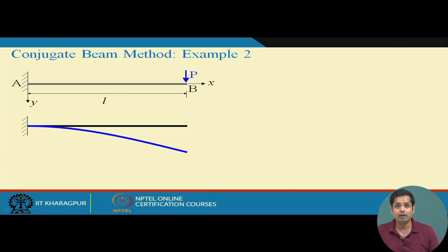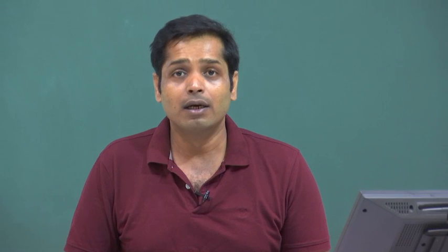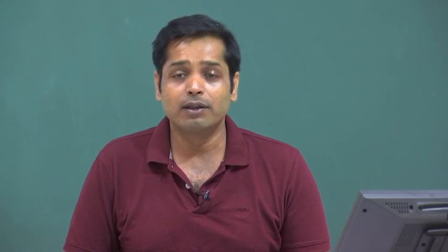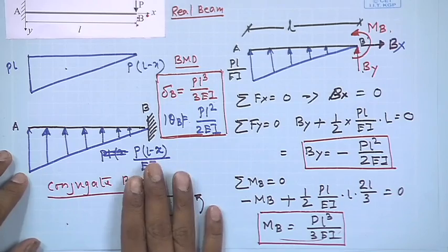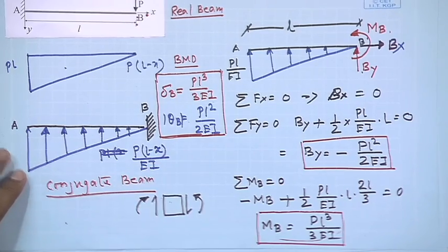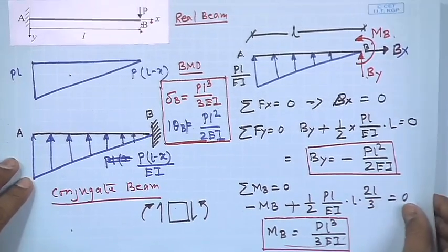Every time you determine the deflection at any point, try to understand intuitively what would be the probable deflected shape of the beam. Then see that the deflected shape is consistent with the bending moment you get and the sign convention you used. Okay, this was the first example.